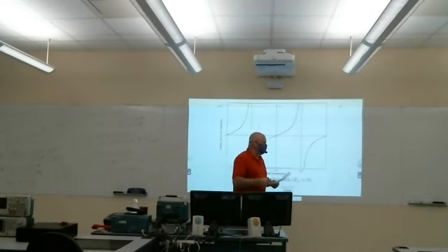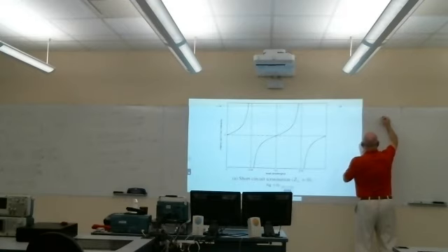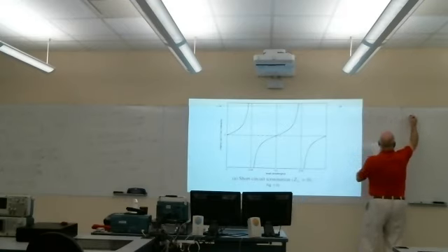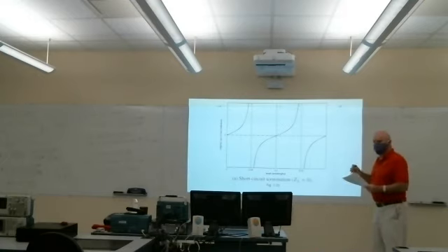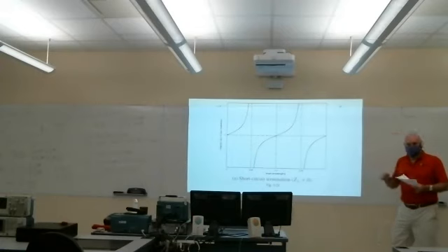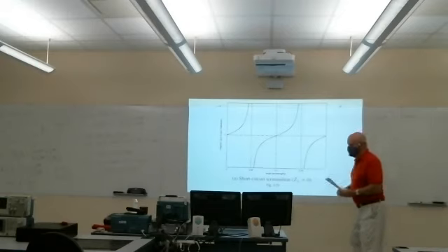Okay, these things are called transmission line stubs, because they can also often be put in parallel with a special coax connector, a T-type connector that actually allows you to just hang off a piece of transmission line.